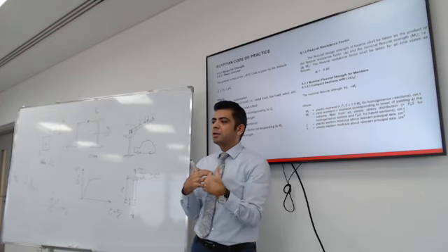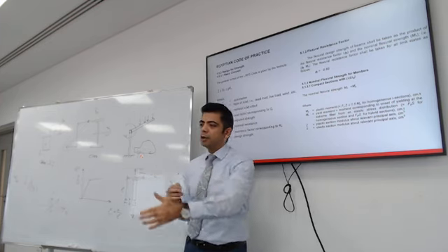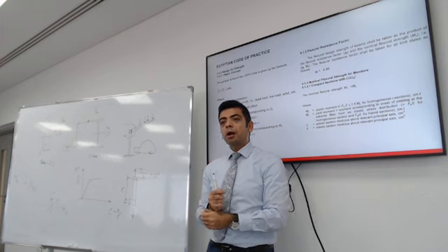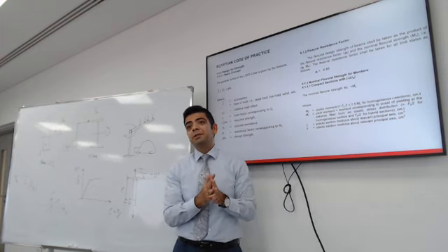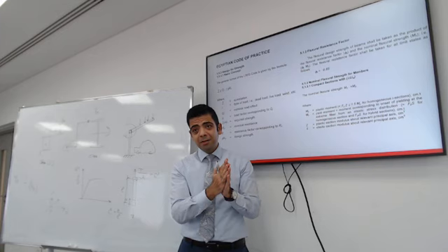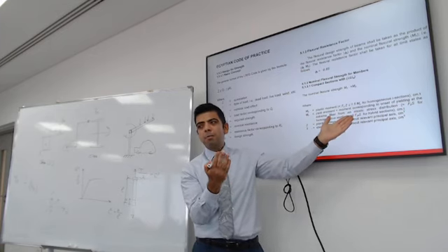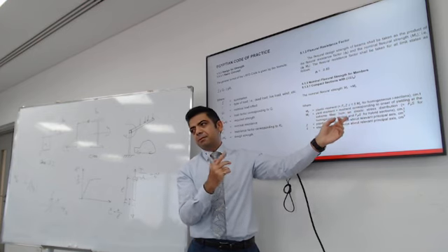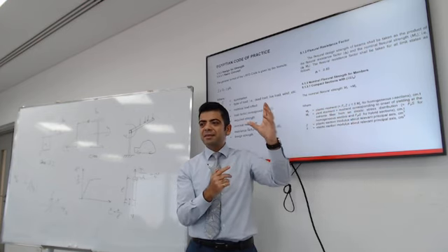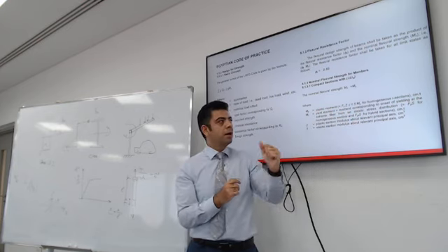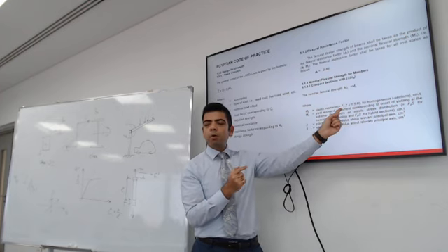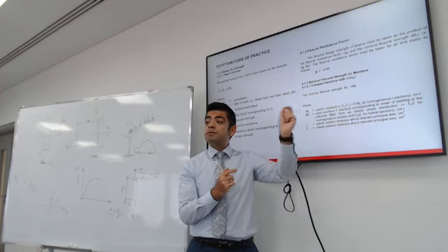You understand what needs to be done. So what if you were hired to design a structure according to the American standards? Just get the document and see what they call these values. They're probably going to call the section modulus Z and S: Z for plastic, S for elastic. Pretty much everyone calls yield strength F yield.